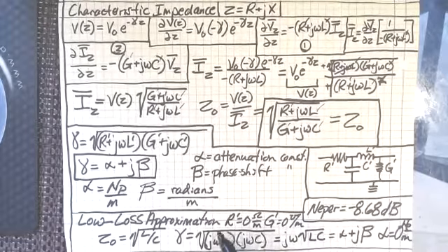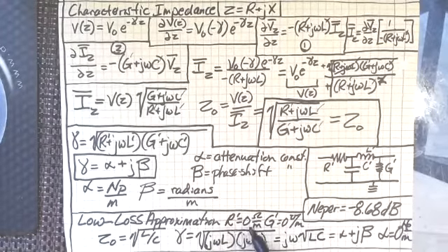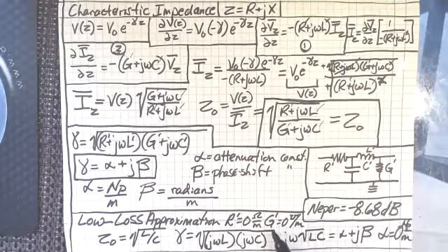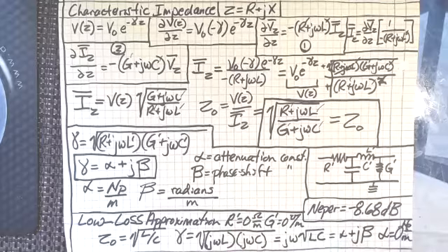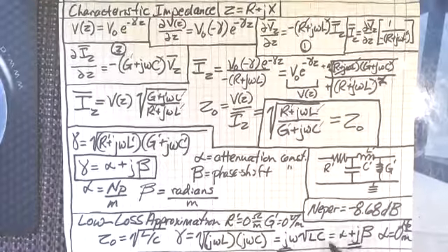No. But we don't have a superconducting conductor as the ground shield and as the signal line. So if we don't, then this is not real, is it? I mean, if this were real and we had a superconductor and there was no loss whatsoever, no resistance per unit length, then we could make this approximation, and of course we could send unlimited high frequency signals over that all the time and never have a problem. It doesn't exist. There's the problem, right? Because that is j, and that is j, and there's nothing without a j in front of it.